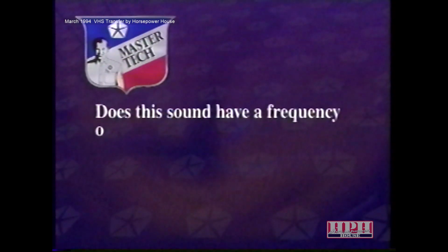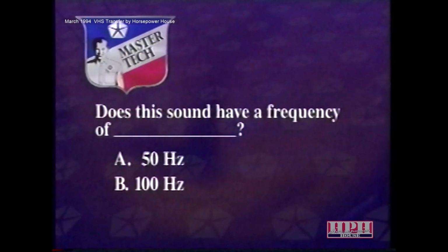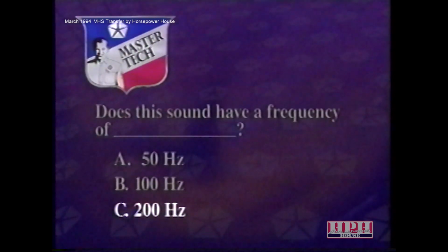Let's test our abilities. Does this sound have a frequency of A, 50, B, 100, or C, 200 Hertz? If you said C, 200 Hertz, you are correct. Your ability to recognize vibrational frequency levels is important when determining which components are causing excessive noise and vibration. We'll demonstrate this later on during step 4 of the troubleshooting process.